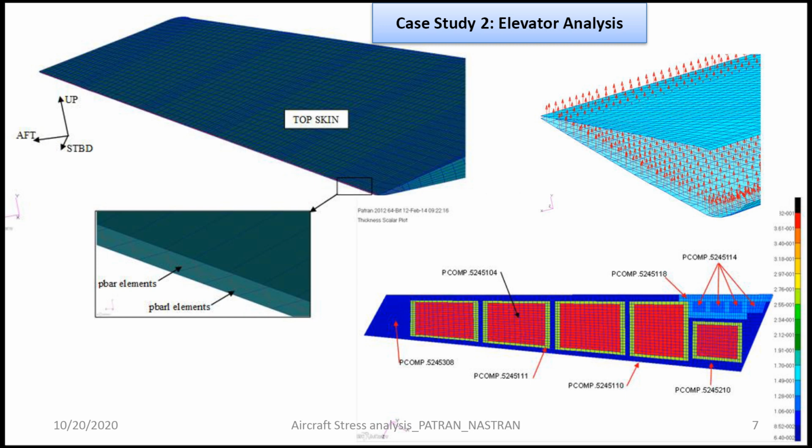If you look at this slide, you will understand that the mesh is not that fine. It's a bit of a coarse mesh. Since it is a 2D mesh, I went with fully quad elements. I tried to minimize the usage of trias wherever possible.